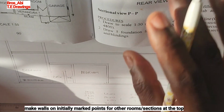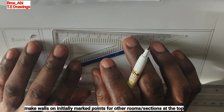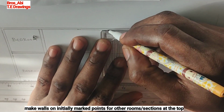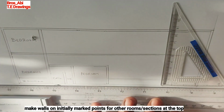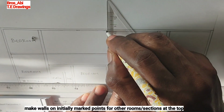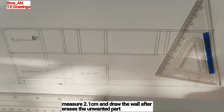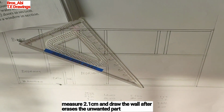Okay. So now let's move to the upper part. Since I've marked out this point here, let me just build my wall. Meanwhile, from here to the top here is 2,100. So let me measure my 2,100 from the bottom.